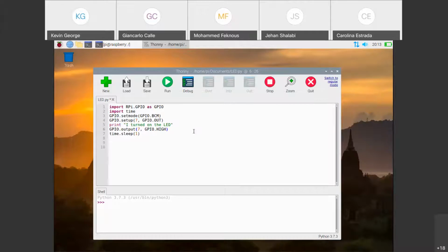Moving forward, we're just going to add in this snippet of code before I put in that delay. This will actually tell our LED to turn on. This is going to be a high voltage state, so that means our LED will be given the full 5 volts, of course going through the resistor so that it doesn't burn out. And now we can delay that. And then once we wait that 1 second, I'm going to tell our LED to turn off.